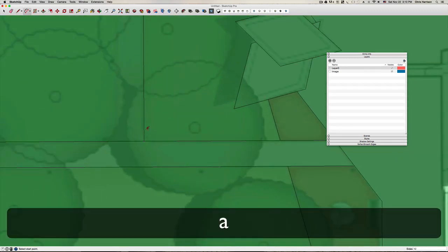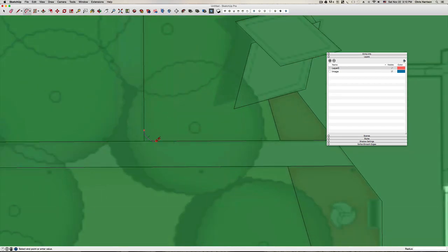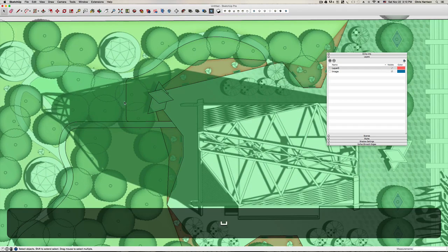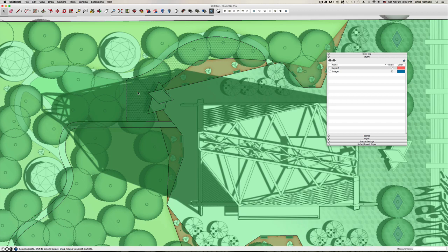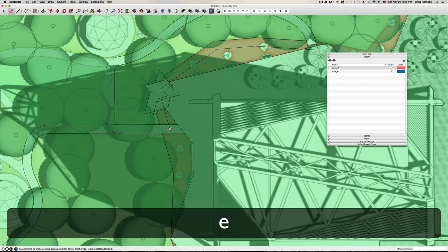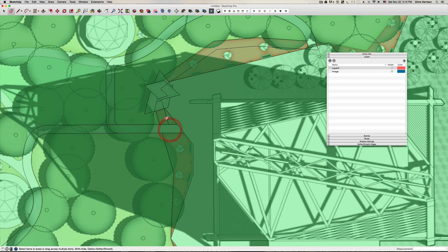All right, it looks like arcs there, and I'll just delete that. And kind of using that same principle again, I'll click there and then I'll use the offset. And I know that that's supposed to be 6 feet. Okay, and I'll just come in here and delete the extra line work that I don't need. All that can go.